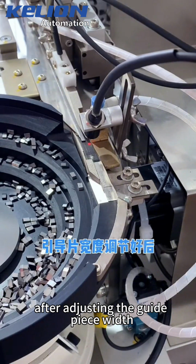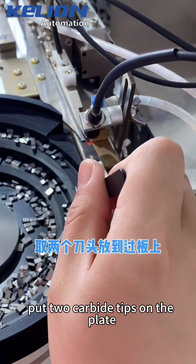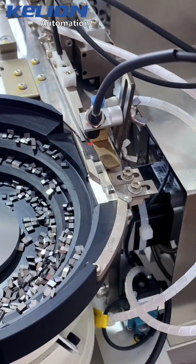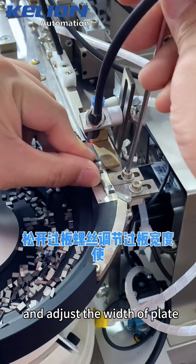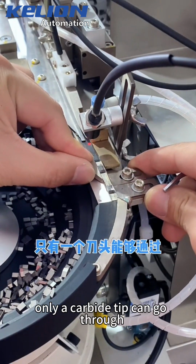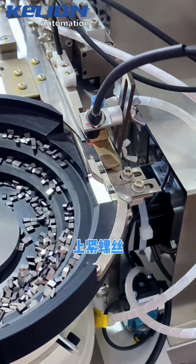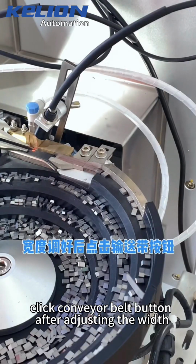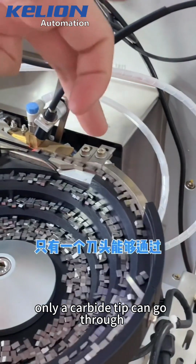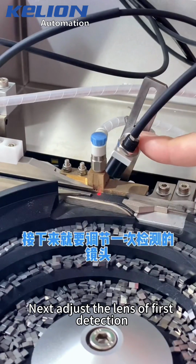After adjusting the guide piece width, adjust the plate above the vibration plate. Put the carbide tips on the plate. Loosen the plate screw and adjust the plate width so that only one carbide tip can go through. Tighten the screw. Click the conveyor belt button after adjusting the width and see if only one carbide tip can go through. Next, adjust the lens of the first detection.